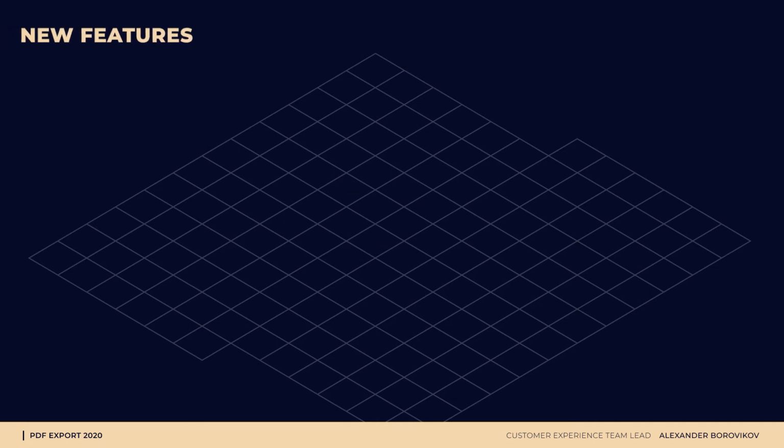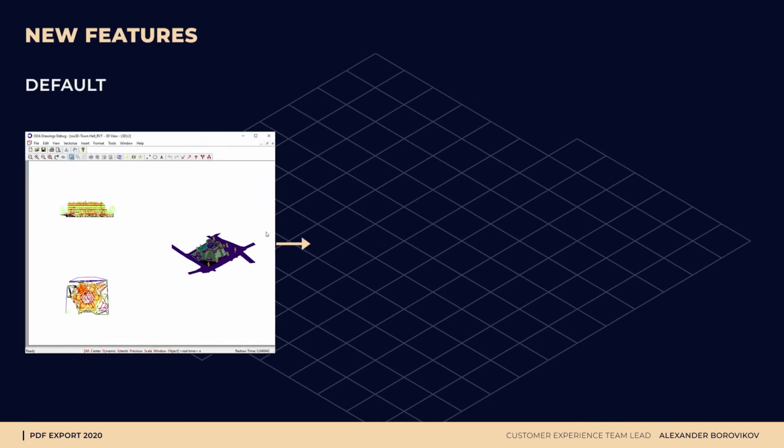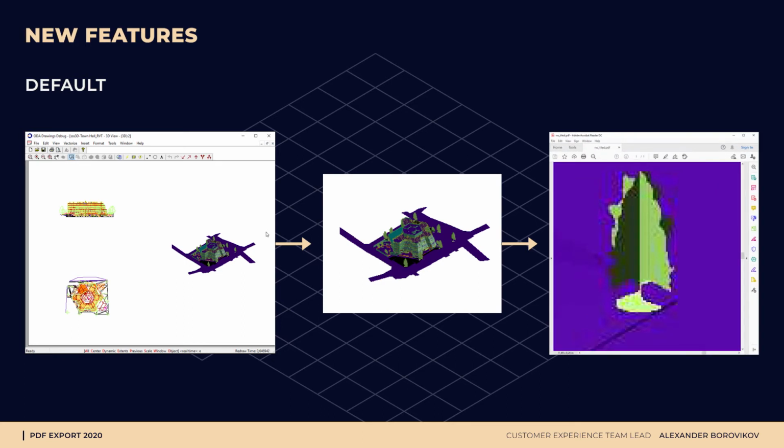The next point, high resolution support. There is a render mode in ODA SDK that displays 3D figures named shaded. Sometimes we want to export those figures to PDF, but in PDF export we don't have such mode, and thus they're exported as bitmaps with the low resolution, which is quite sad. This situation was recently improved. It was improved in the following way.